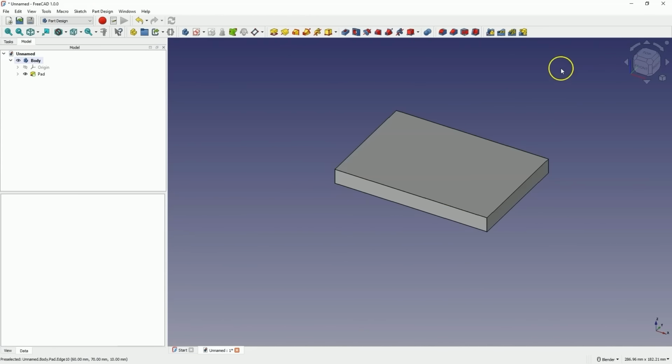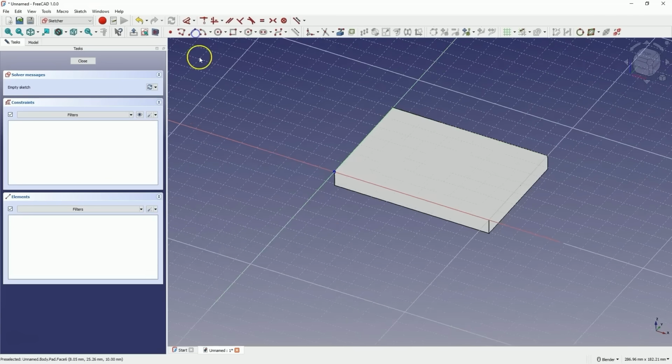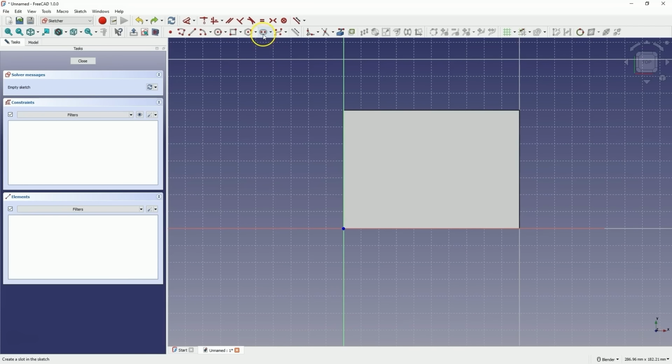Here we will create another sketch. Select this face, choose Sketch Creation. Now select the Draw Slot tool, place the first point of the slot here, then specify the dimension of this slot. Enter 20 millimeters here and hit enter. As for the angle dimension, type in -90 degrees so that this slot is parallel to the y-axis. Now enter 4 millimeters for the width of the slot.